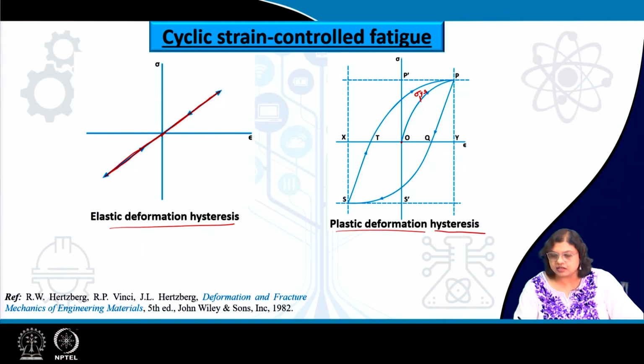So, that means that it is having some amount of permanent deformation, and this could be apparent if we are unloading it. So, if we are unloading it, it basically unloads following the elastic slope, and that means that some part can be recovered. So, this is actually recoverable strain.